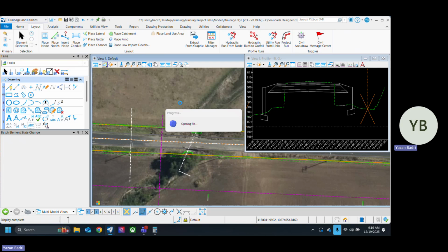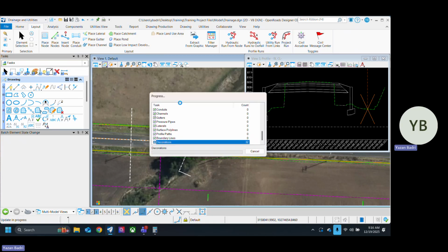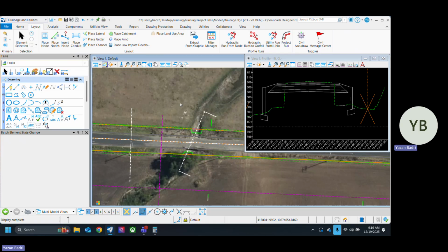Just a quick question on this: the aerial, where is it coming from? Is it coming from a server somewhere? Yeah, it's Microsoft Bing. See the bottom left. And that's the only server you can get? No, if you have a link to a server, you can add it in here also, in case one's newer than the other. You can add a link like a WMS server link, but you have to apply it as a raster. It's not through this default one. This is the default aerial.